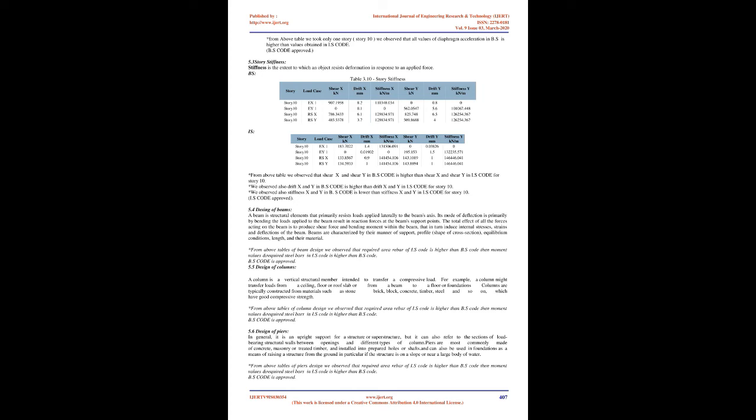5.1 Response spectrum functions. Response spectrum is a plot of the peak or steady-state response, displacement, velocity or acceleration, of a series of oscillators of varying natural frequency, that are forced into motion by the same base vibration or shock. The resulting plot can then be used to pick off the response of any linear system, given its natural frequency of oscillation. One such use is in assessing the peak response of buildings to earthquakes.